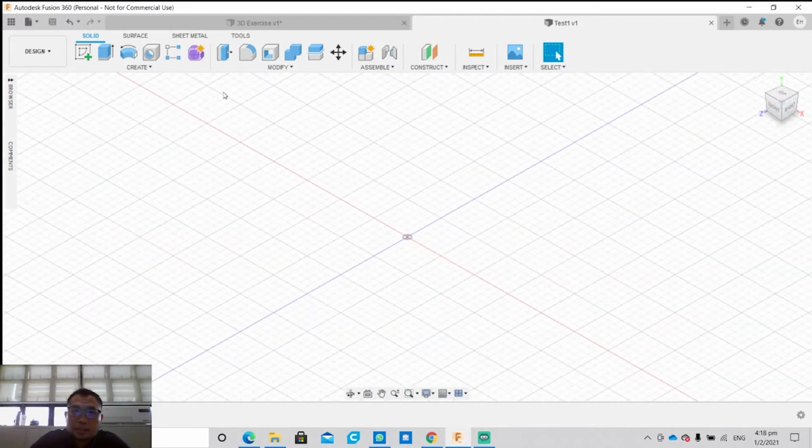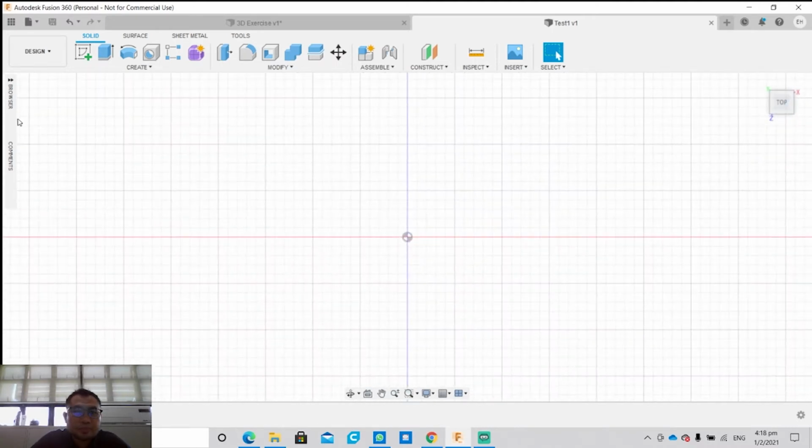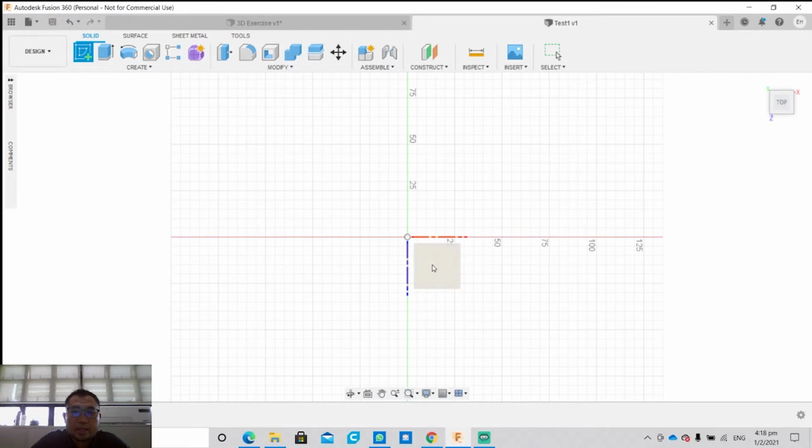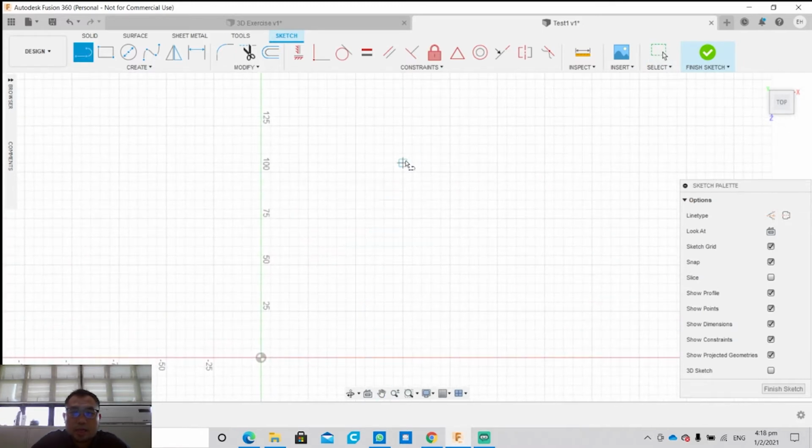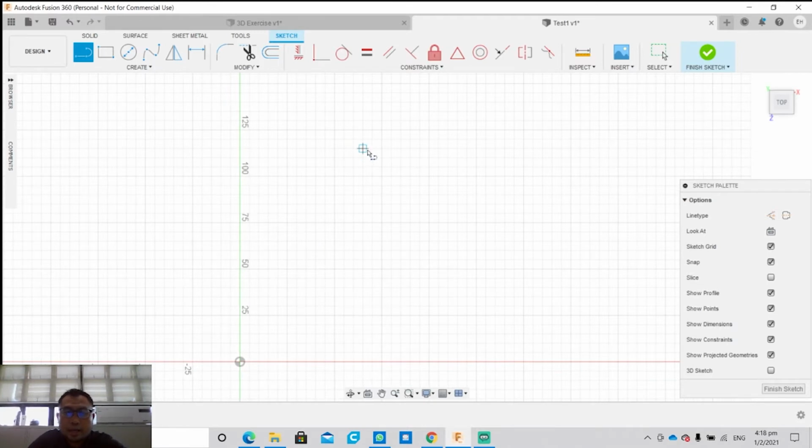So when I start my sketch, I go from the top view and create a sketch. I click on the plane, the top plane. So I start with a line. I orientate it such a way that I am on the positive dimension of the top plane. So I am going to place my first point, and my second point is about, you can enter the dimensions that you want. The base of the triangle will be 140.